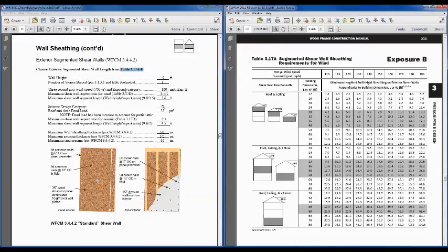And we've got, again, a wall height of 9 feet. Number of stories braced is showing up as 1 because we're on the 2nd floor. So one quick note here for seismic design. In section 3.1.3.1 that's referenced here, if we had a full attic all the way across this building, that would actually be treated as a second or an additional story.